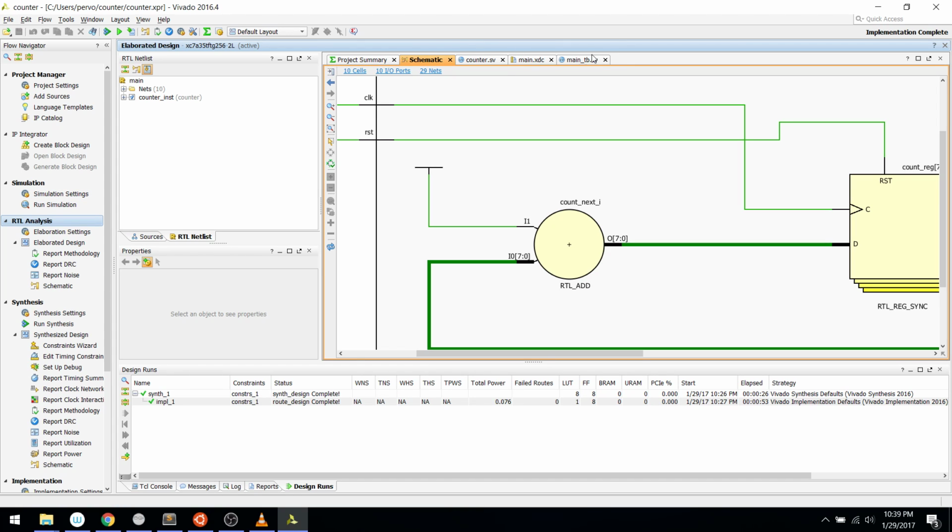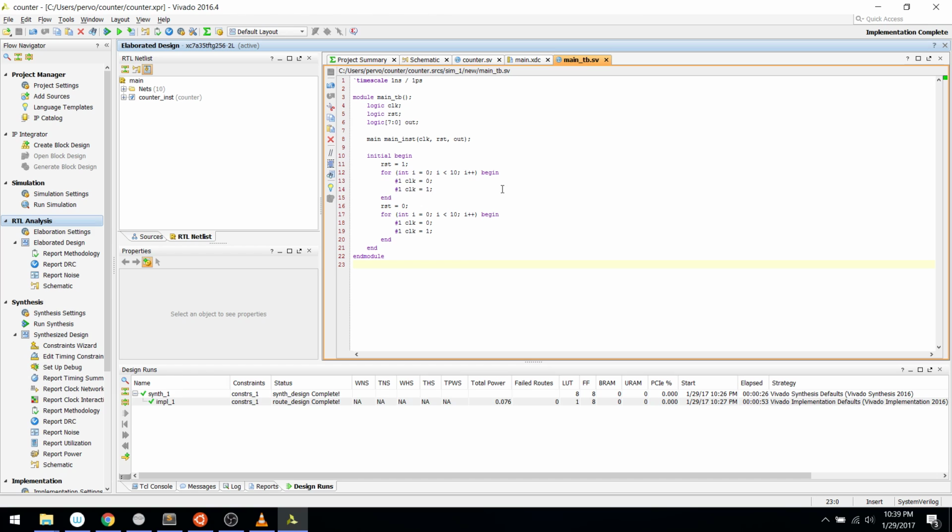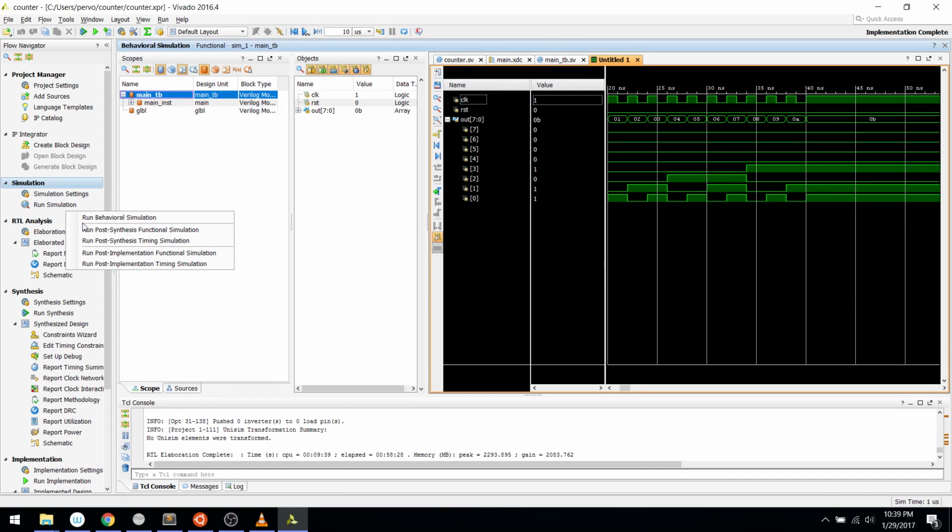Basically what it's doing is taking the Verilog code that you wrote for the test bench, and taking whatever the netlist represented in Verilog form for a given compilation pass, probably after optimization and so on for some of the later passes, and running it against this code. So for basic functionality, it's good to start with behavioral, but you want to use some of the later phases in order to capture any logic optimization that may have changed behavior.